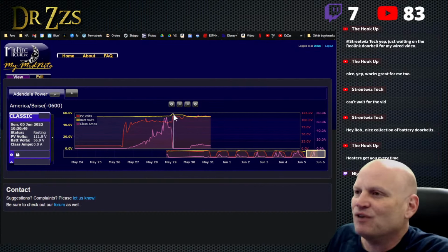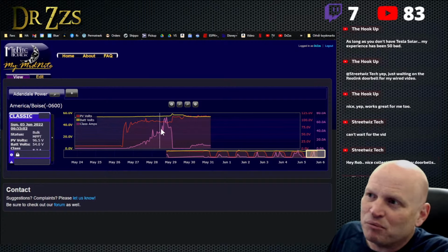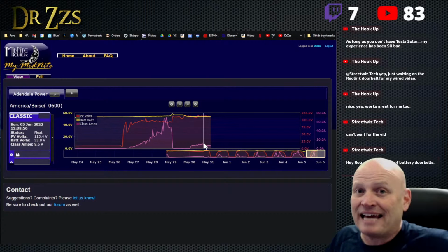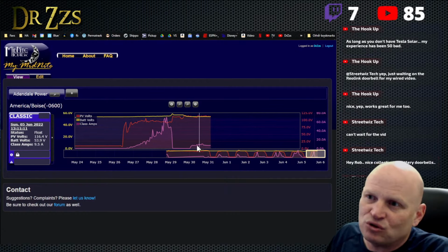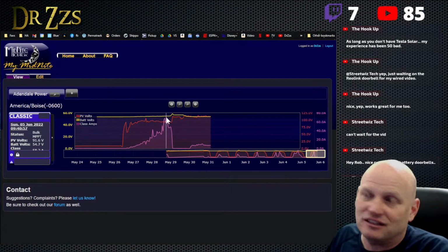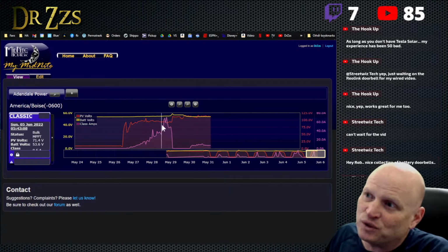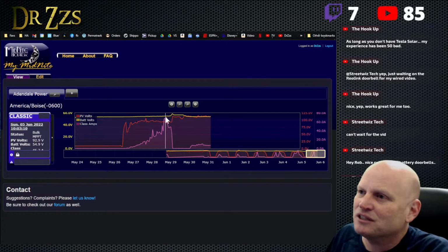So that's kind of okay. I mean, the important stuff here is that it gives me the battery voltage and it gives me the solar array voltage. The purple line is telling me when it's adding charge, so it's telling me how many amps it's charging at. Right now it's charging at about 8 amps. There's times when the batteries are dead and the sun is full blown. You can see how the charge went today from dead batteries. Sun comes up, boom, right up to what it can do, 90 amps. I think the highest number that I saw was maybe 70 amps.